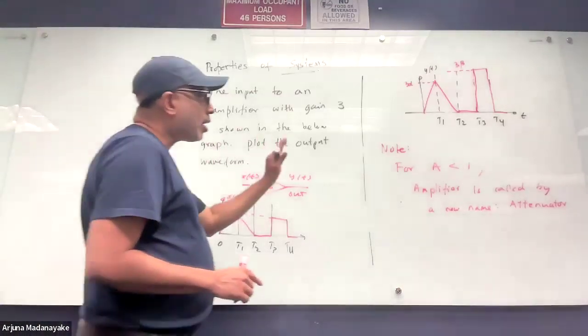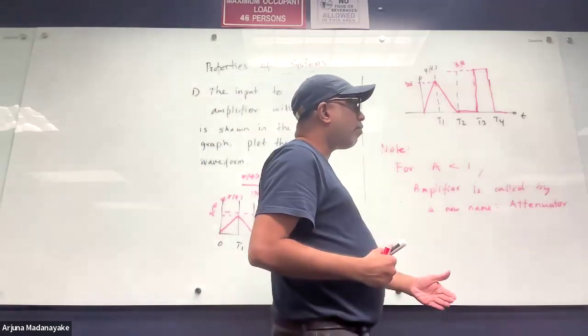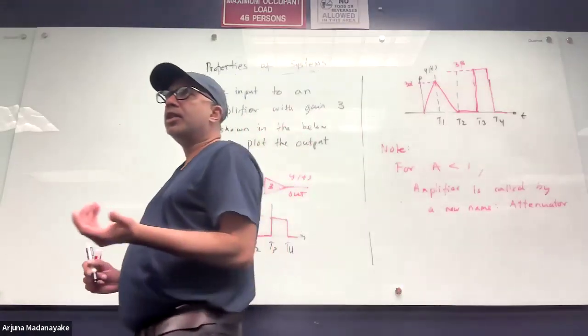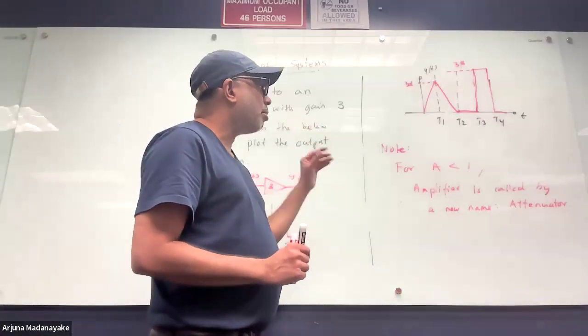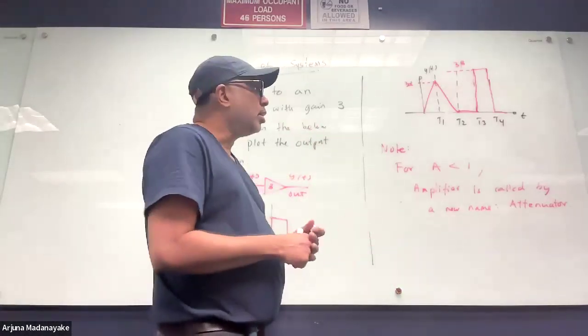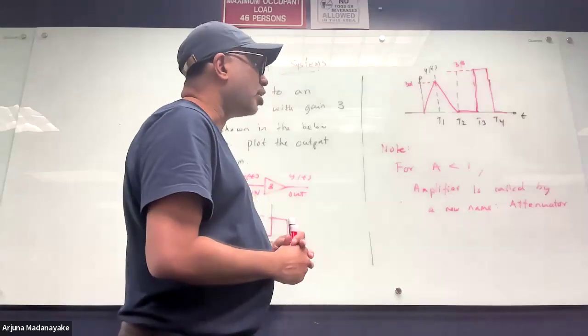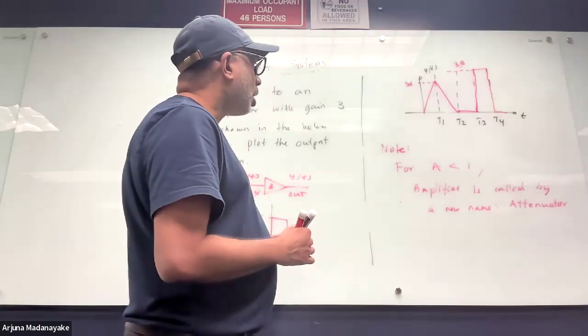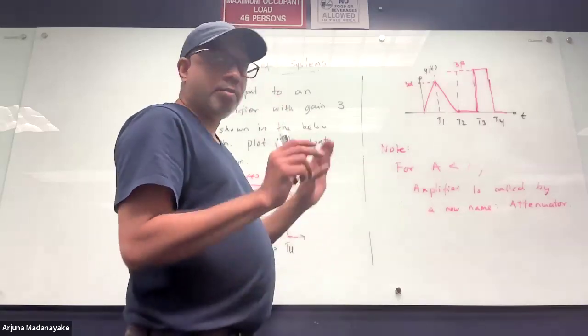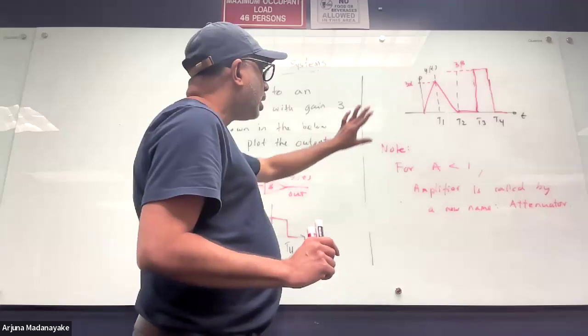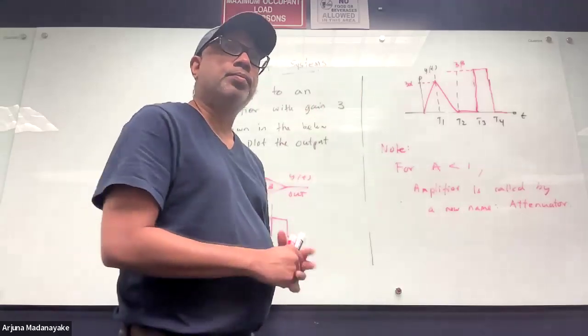So typically amplifiers which are less than 1 gain can be realized without any power source. It's a lossy circuit. So you can basically make the signal smaller very easily. It's basically called an attenuator. But even though the circuit types for amplification and attenuation are completely different, mathematically they appear the same. It's just scaling the input.